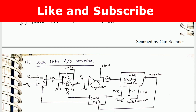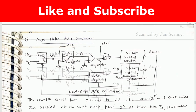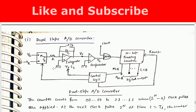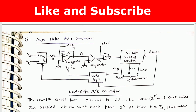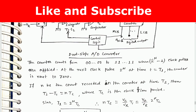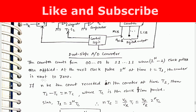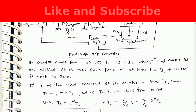Dual slope means two op-amps will be there, two comparators will be there. This is a very complicated circuit, but you have to remember a few key points to identify what type of converter this is. Dual slope: two op-amps will be there and an n-bit binary counter will be there. The counter counts from 0 0 0 0 0 to 1 1 1 1 when the 2 to the n minus 1 clock pulse is applied. As the next clock pulse to the n arrives at time t equals t1, the counter is reset to 0.